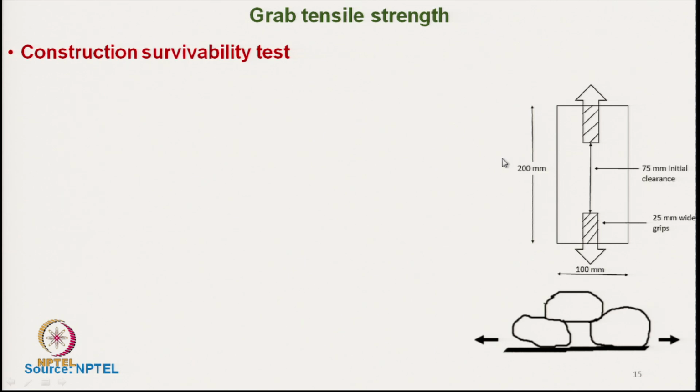In grab test, the geotextile sample is not gripped throughout the width, it is gripped at the center. This situation normally occurs during application.